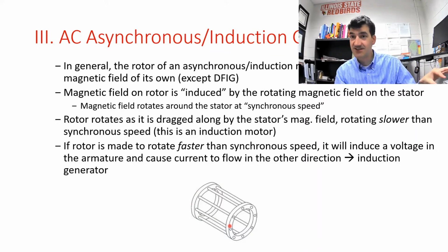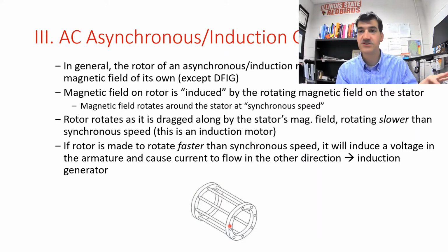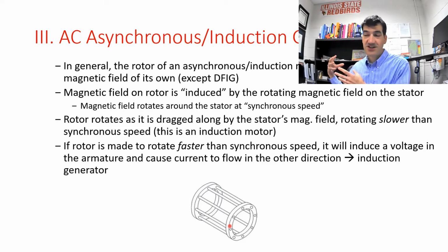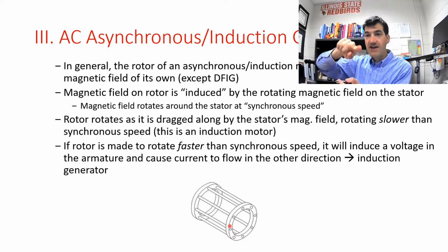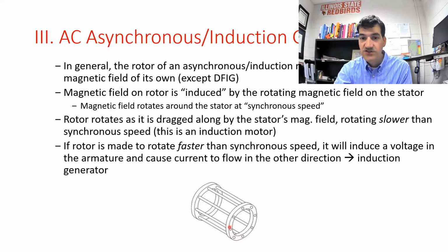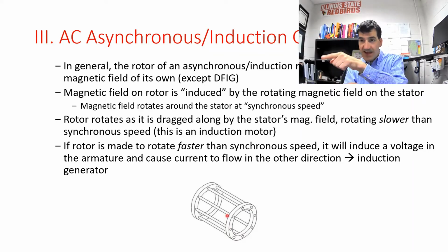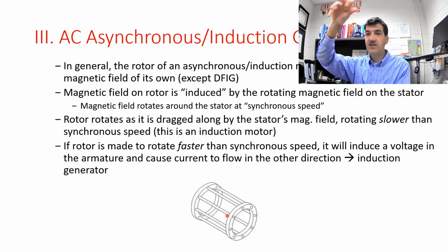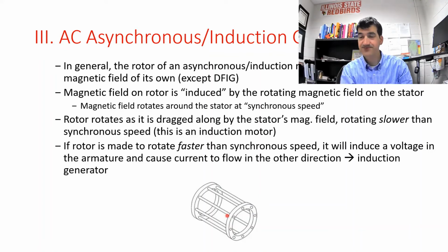And we talk about that in TEC 240. Once again, we talk more about motors in TEC 240. So if you're interested, then feel free to take that class. But we can actually do something very slight to turn that into an induction generator. All you have to do is attach a turbine of some sort, maybe a wind turbine, maybe a hydroelectric turbine, anything to drive that rotor, this rotor right here, to drive it around faster than the magnetic field is rotating around on the stator. All right.